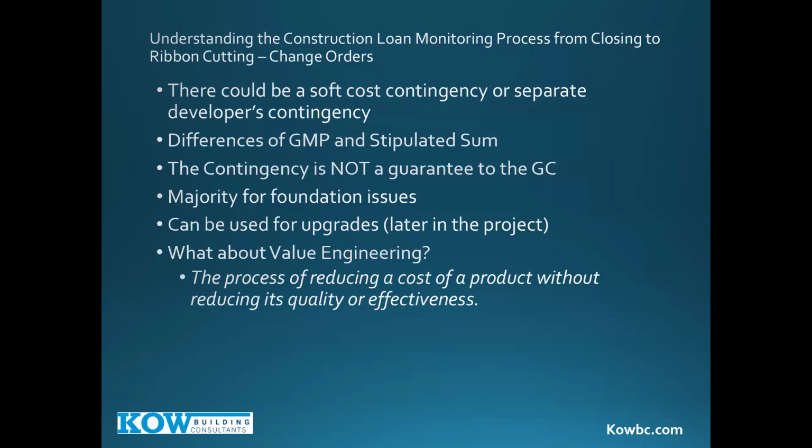And in our stip sum project, it's going to be a closed book. And this is a critical point. I would say to you as the contractor, hey, you're going to get my G702 and 703 each month. You're going to get my partial lien waiver, and you're going to get my change orders. But what I do with my subs is my business.